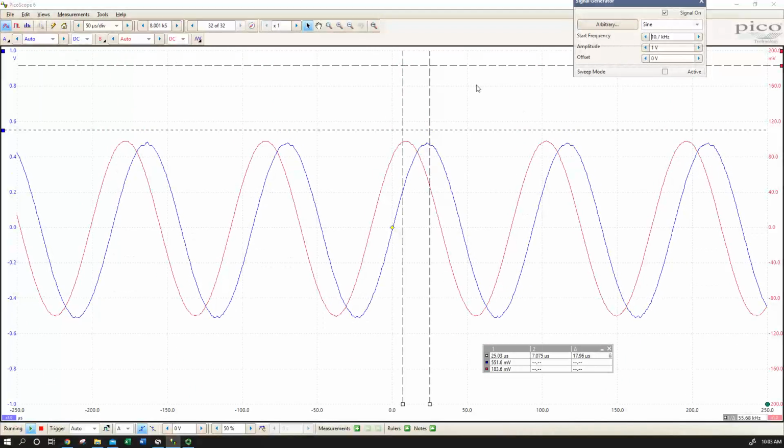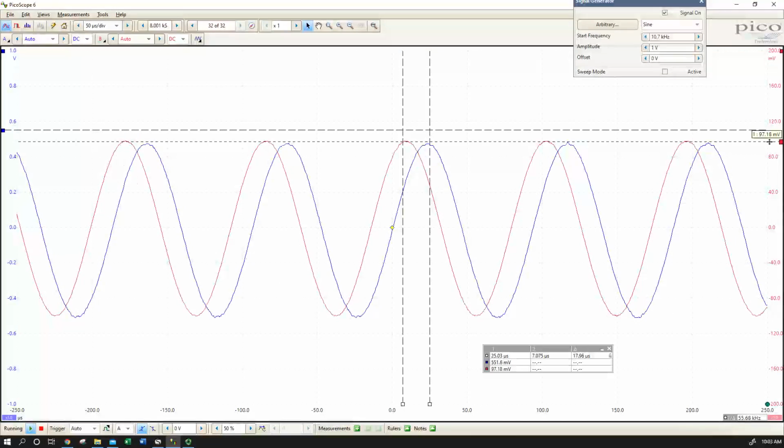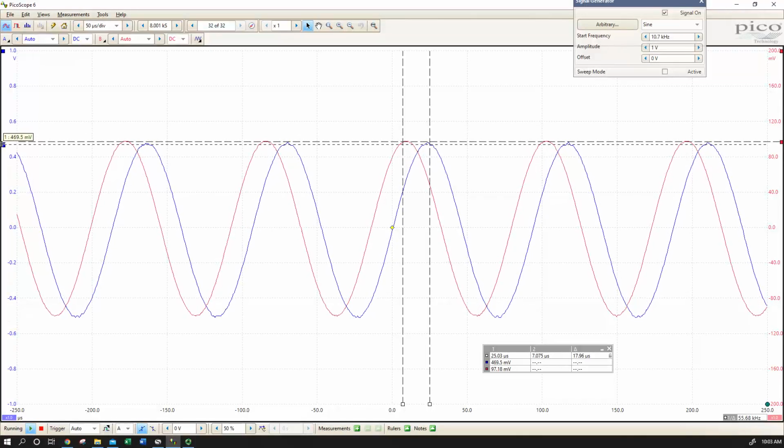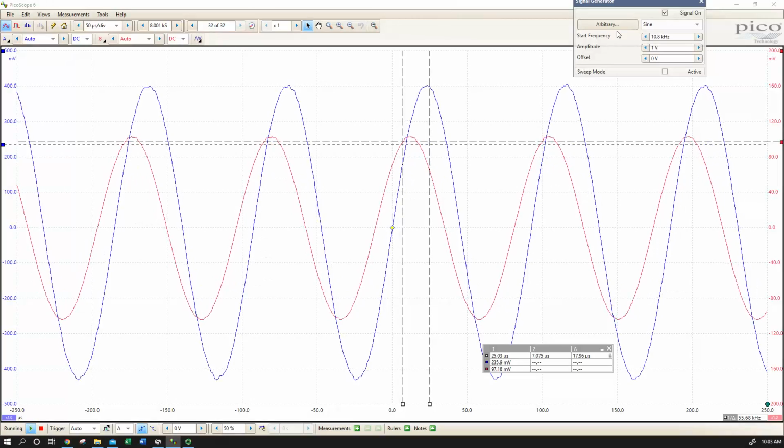And we've had another scale change. So now our channel B is scaled up to 200 millivolts. So now it went up about another millivolt, and the total voltage drop over the circuit is now 471. So we lost more of that capacitive reactance, and our peaks are drawing closer together. So let's creep up a little more.